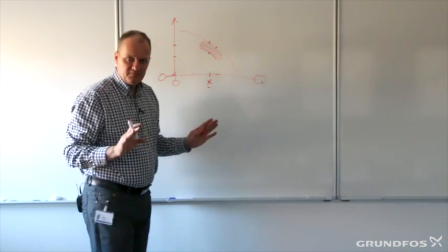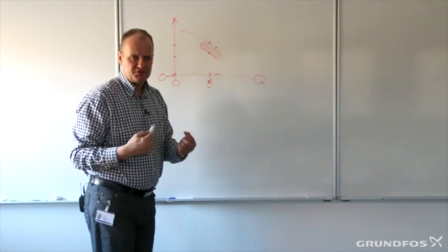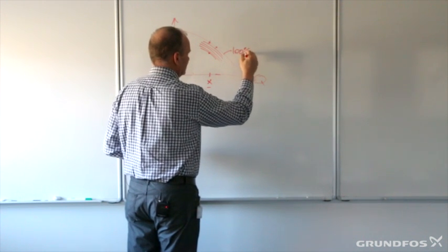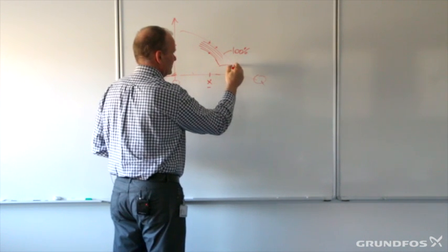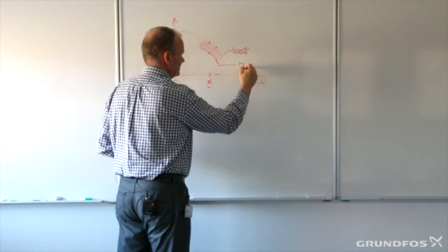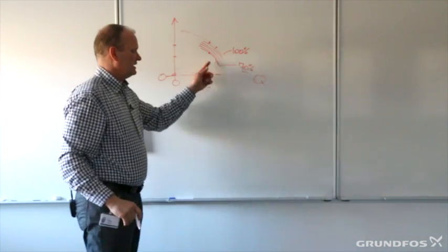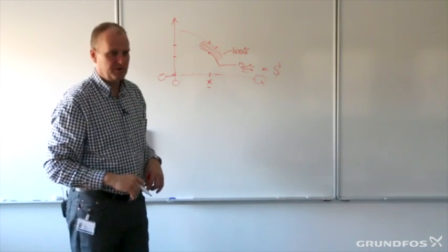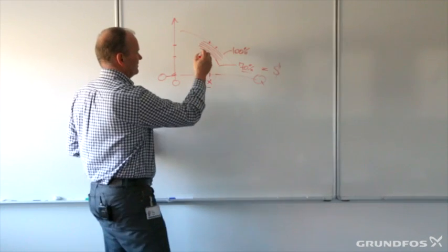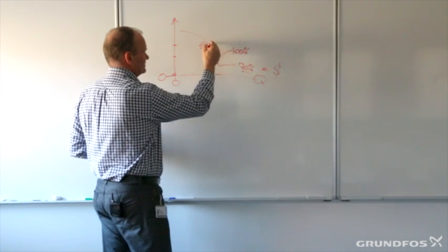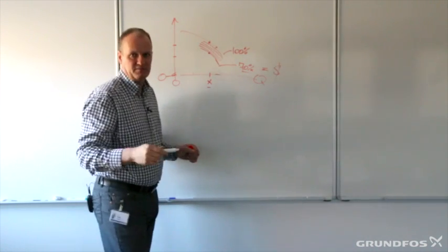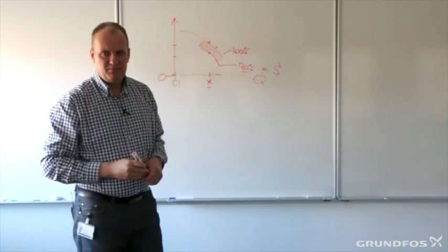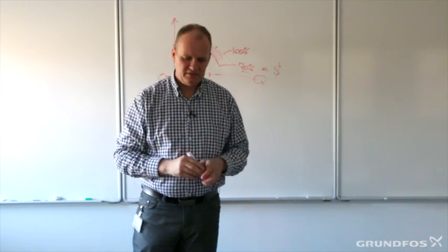And then the pump is still operating with fixed speed. So if this is 100% rounds per minute, this one could just as well be maybe 70%, and that's equal to saved cost of pump operation. And also the fact that in the other situation we needed to equip the system with a balancing valve or throttling valve, this valve can now be eliminated from the system. So we're saving initial cost here.